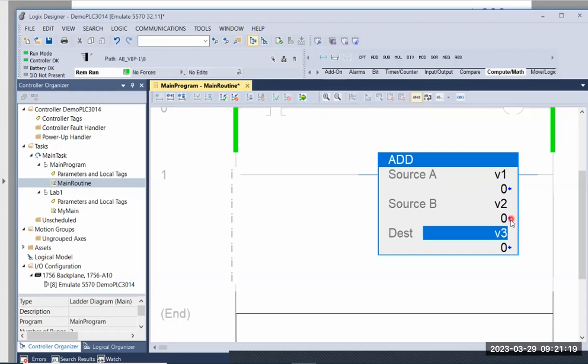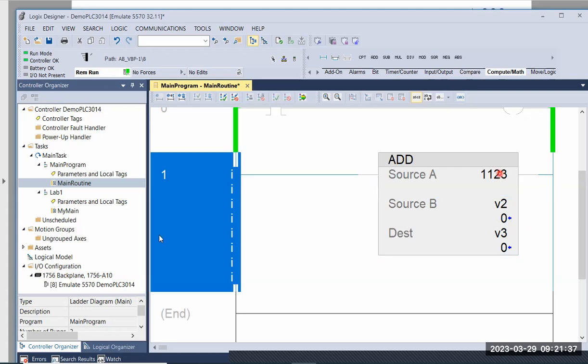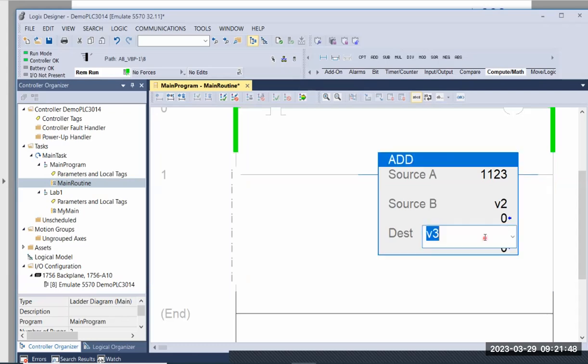And you can see all zeros below there. They're representing the current value of the tag. So this is one source format. And you can change that to a value, which would be immediate. You can see here, when I change this, it doesn't complain. It didn't show an error. If you see an E, that's an error. But if I change the destination to a value, you see here there's a red X, so that means error.